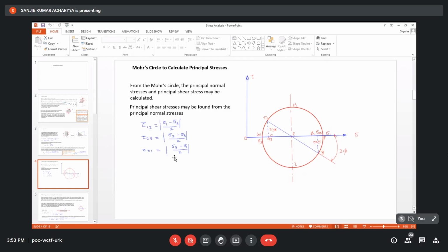And if the material is ductile, some mild steel category, the designer has to check with the shear stress. Instead of evaluating principal stresses, he will calculate the maximum shear stress, check it against the permissible shear stress of the material, and make the design complete, finalizing the dimensions. This is the designer's role. And to implement this efficiently, you have to know material science, material behavior also. Am I right?